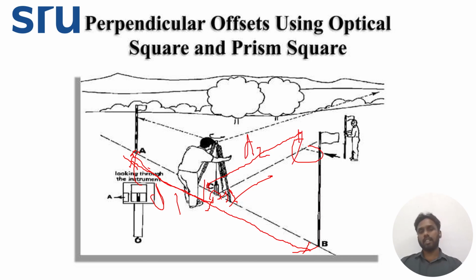So once you have measured these things, only then can you transfer this reading into your drawing sheets or map to locate a particular structure for marking of your offset. Okay, so these things you should be cautious about while doing your perpendicular offset, and while you are using cross tabs or your prism square. So this will give you exact 90 degrees.